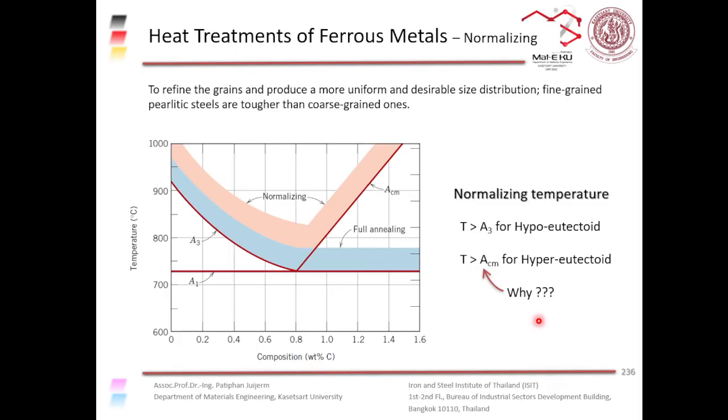So basically, you have some sort of hardness or strength in mind, and with that hardness and strength in mind, you know what sort of grain size you want. So we want to heat it up and then cool it down relatively quickly to get that grain size, to get the designed microstructure and designed hardness. And to achieve that, we have to sort of reset the whole microstructure.